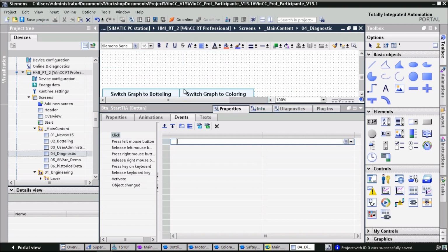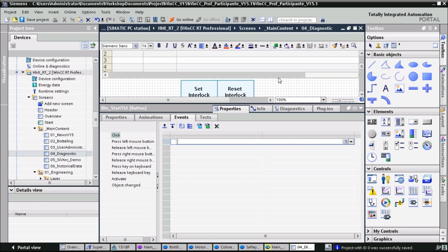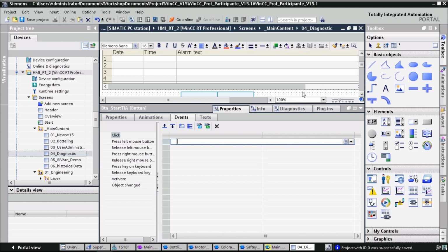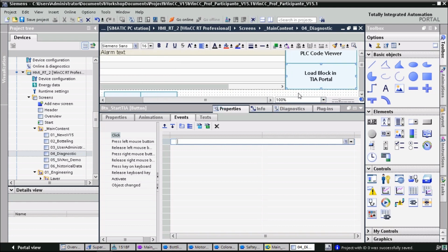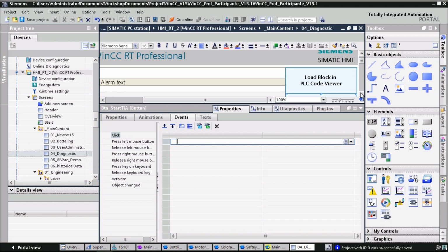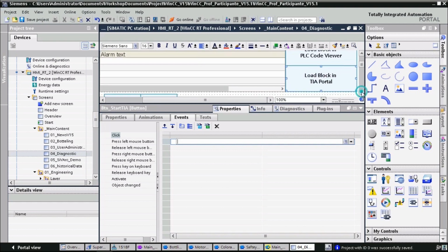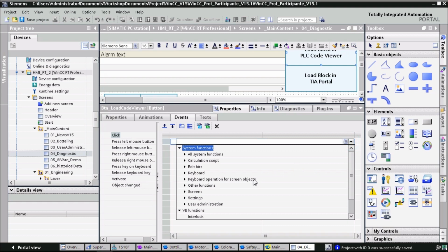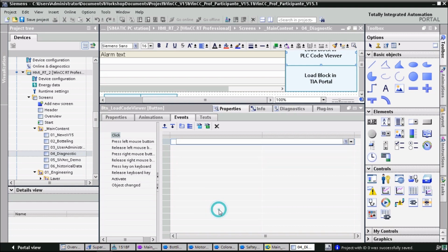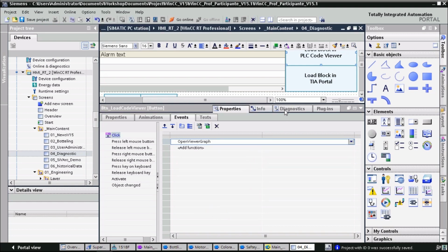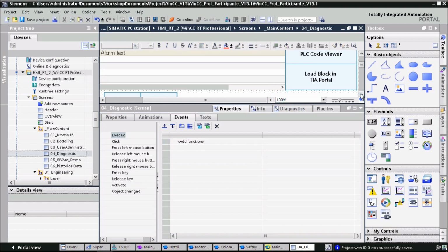And now we have to fill it with the parameters. It actually already uses the objects on the screen. Alarm screen name is the same screen you're in, because the control is placed in the same screen. Alarm view name is the name of our alarm control, which in that case is AlarmView_1, so that's correct. And our basic screen name is also this one. We can also use it in a screen window, but in that case it's a basic screen, so we don't need to name any screen window.